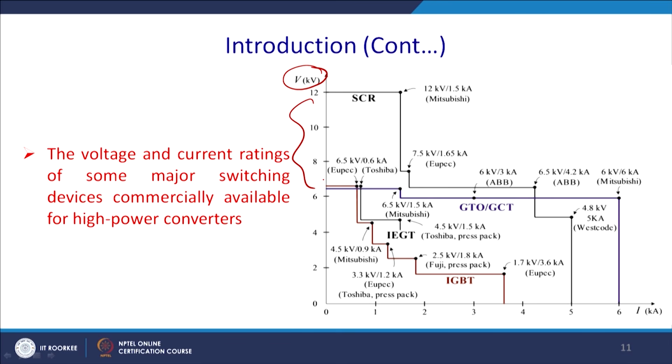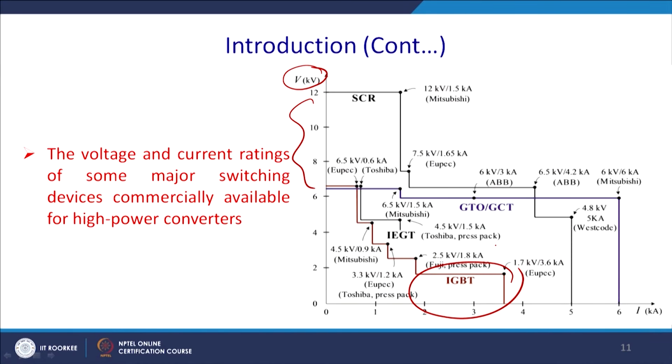Thereafter, in the same way we have the IGBT. If you wish to choose a higher voltage rating, then the current rating required has to be low. So, for high power applications we require paralleling of the IGBTs, or we require IGBTs with high current rating, or we have to put them in the multi-level inverter format. So, this is the power diagram of these devices available till now. Of course, we expect that this situation will change drastically once we have silicon carbide based devices.